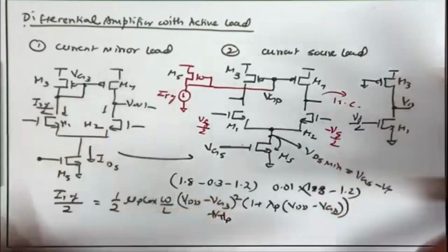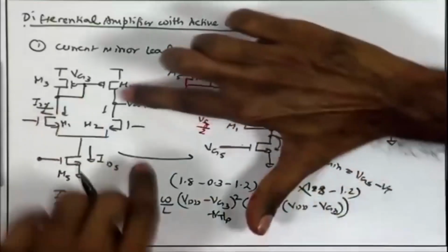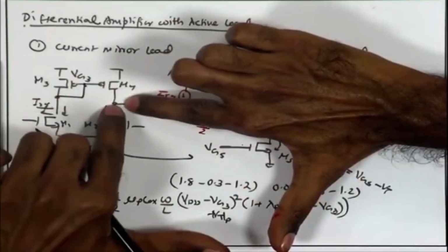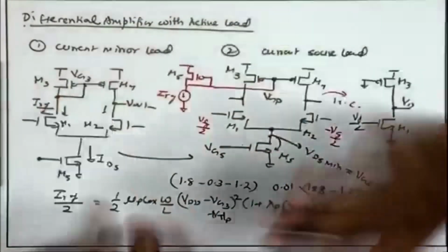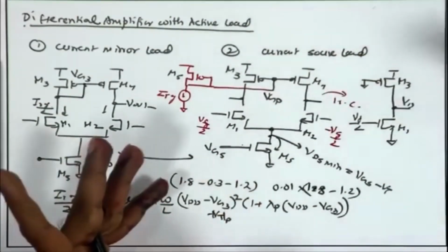And as a result, for common mode operation, I am looking at only the DC conditions, these two branches being very well matched, the V out over here, the DC condition is going to be equal to Vg3. So, we have a very well defined DC point, and this can be used to help our first amplifier, which has an ill defined DC point.